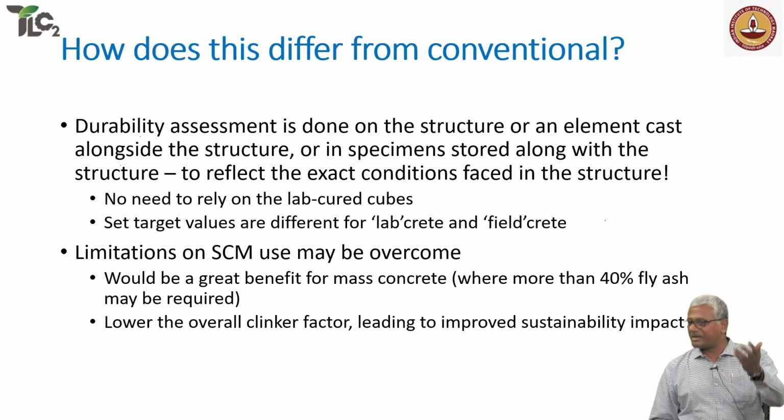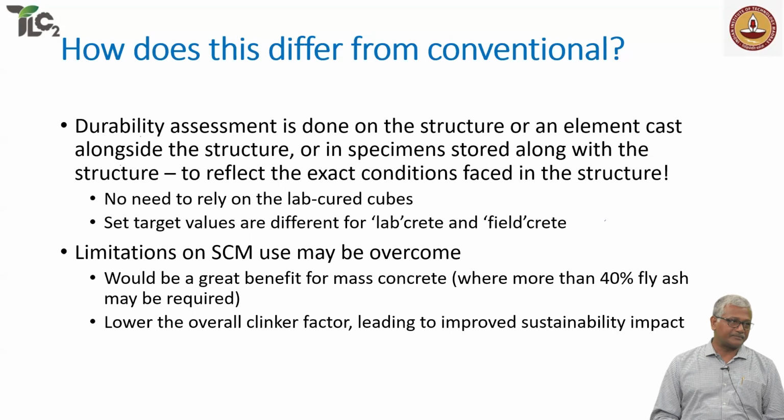This concrete was getting placed late at night, probably very few people actually checking. And secondly, concrete may have been standing for too long and the site may not have been ready to receive it. As a result, the delay caused the workability to drop. They added more admixture to increase workability, overdosed, and as a result, concrete did not set.